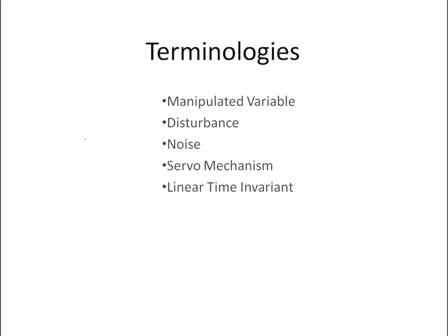And the last topic of today's discussion is the linear time invariant system. Linear time invariant is extracted from the actual system, which varies with time, in which the parameters are changing, and which is also a non-linear system. If we extract a model of a system where the parameters are not changing, that is, the behavior of the system is not changing with time, that is the invariant system, and we are using the system for a certain frequency range where the system is behaving linearly, such modeling will produce a linear time invariant system.